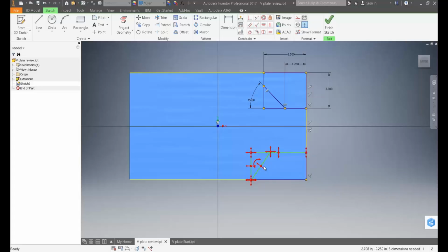All right, so now let's turn around and add some more constraints in the form of dimensions. So we'll put it here, we'll go here, we'll place this at a 45 degree, making it reference the other one. And then we'll add a dimension from the endpoint here to this edge. Bang.